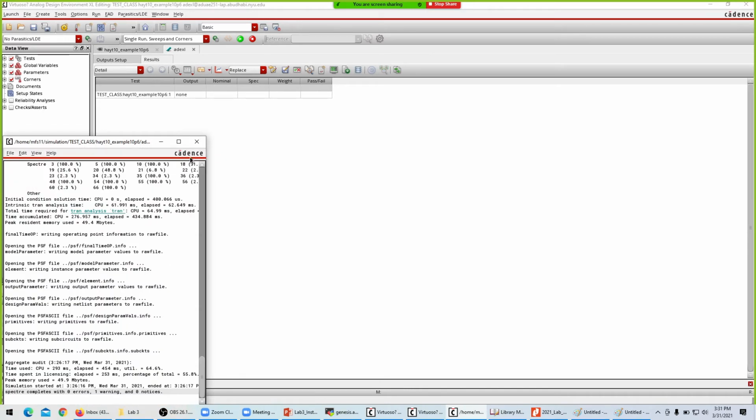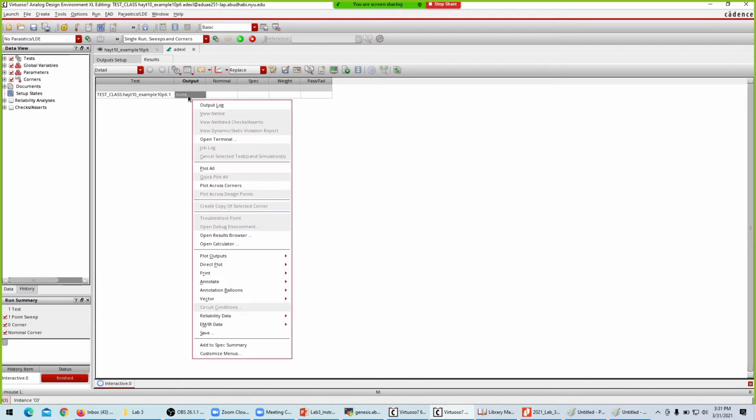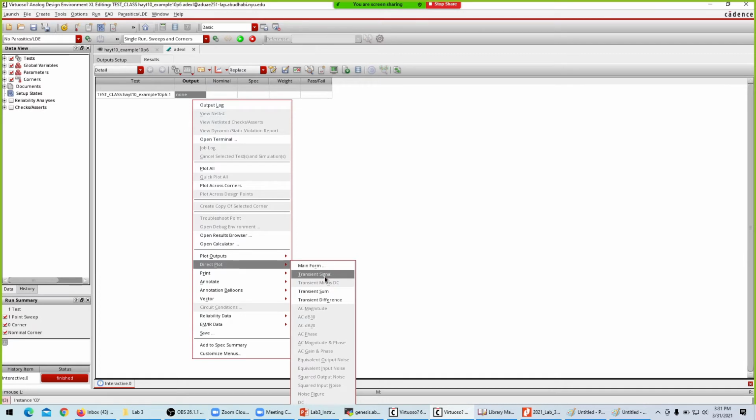Okay, one warning, 0 errors. Okay, simulation is done. So once this is done, now is the time for me to select my output. So what I'll do, I'll hit on none. You see, I'll right click here. I'll say direct plot. Now direct plot what? The transient signal. So direct plot the transient signal.